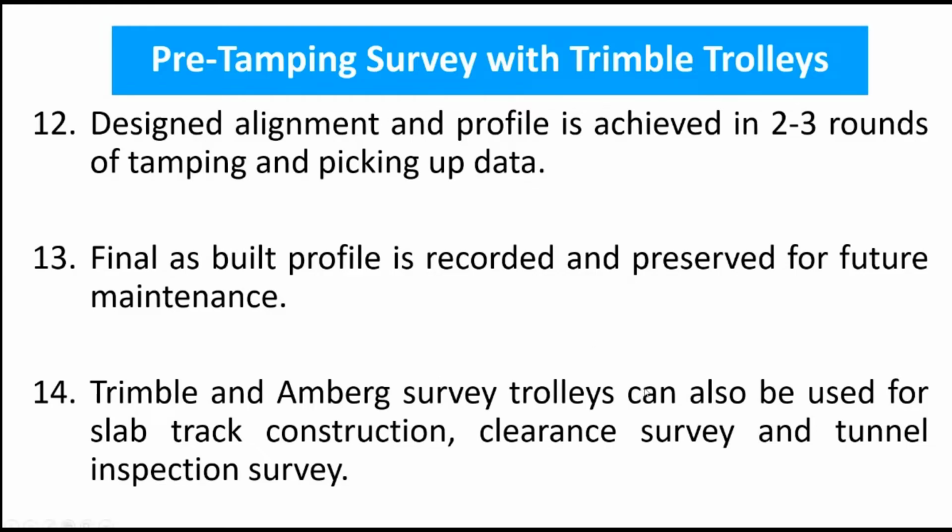They can also be used for slab track and clearance survey of tunnels. In tunnels there is a movement of the inner side, very small, but it is there. So time and again we have to do the clearance survey for any infringement to the schedule of dimensions. That also can be done by survey trolleys.